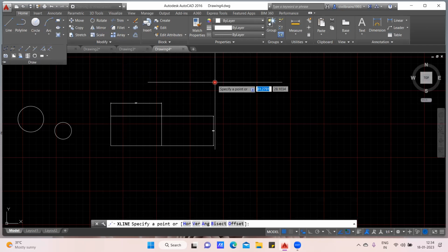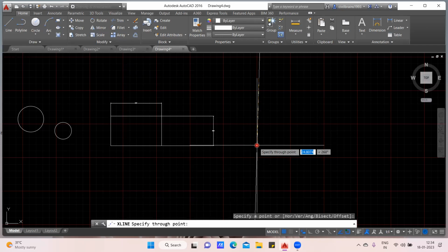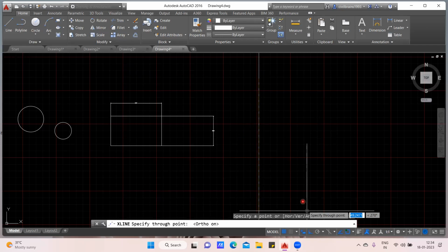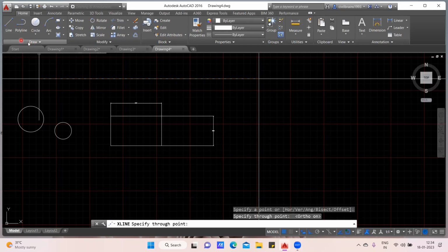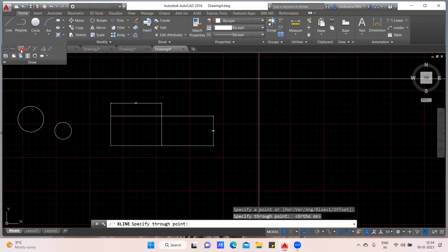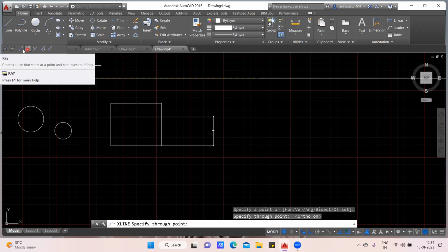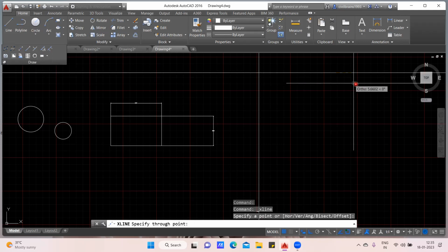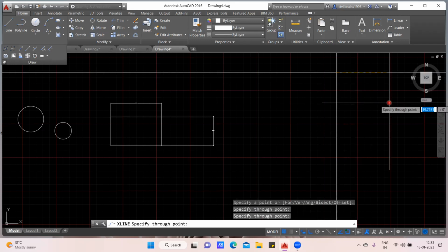For example, now I'll take this option called construction line. I'll click on this and draw a line. I've drawn a line, but that particular tool has disappeared from there. Again I need to come to the draw, and then click on that. Instead of doing that, whenever you want this option to stay activated, there's an option called pin here. Click on the pin, and now you take the construction line from here and make a construction line.